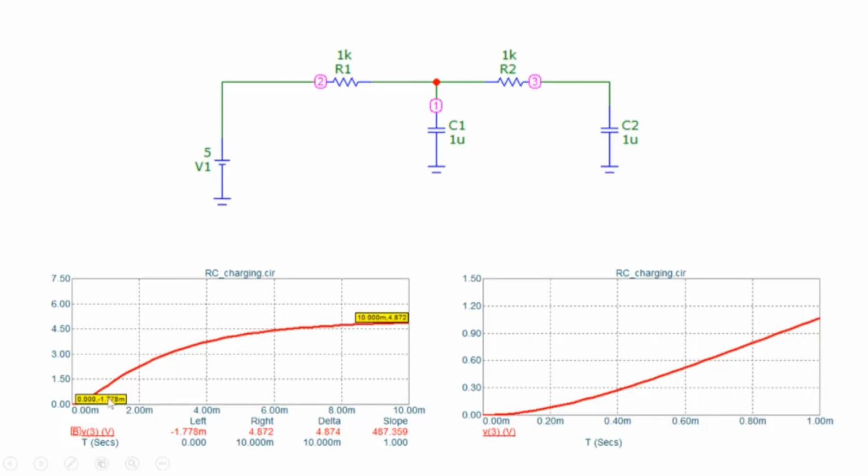But if you examine especially close to this particular part, which is shown here, you can see the charging is sort of odd here. Normally the charging is, if you call this a convex kind of curve, then here you can see some kind of a concave, and initially this voltage is not charging at all, and then the charge across the capacitor starts building up, which we can understand because the charging of C2 depends on the charging of C1.